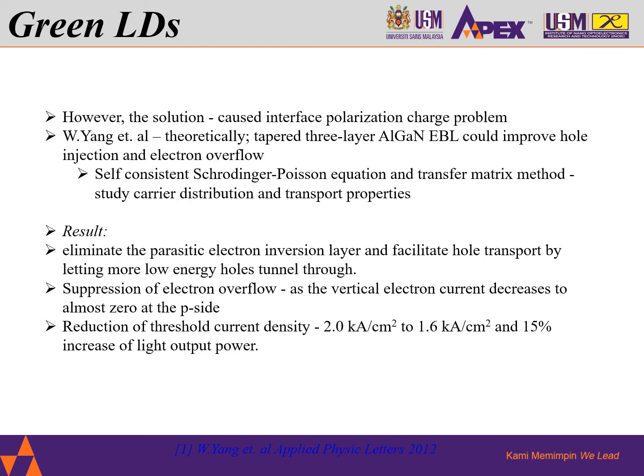However, the solution had caused an interface polarization charge problem. Yang and his team pointed out that a tapered three-layer AlGaN EBL could improve the hole injection and electron overflow, but this is theoretical. He employed the self-consistent Schrödinger-Poisson equation and the transfer matrix method to study the carrier distribution and transfer properties.